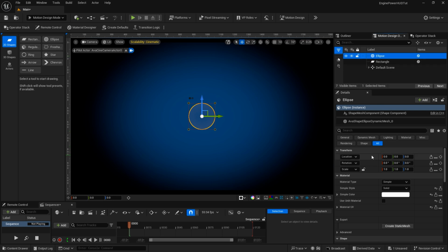So I'm going to bring this forward just a little bit. So I'm going to click on the location X property right there, and I'm going to set that to -1. You'll see now that it pops out in front of our background. Earlier, they were being mixed together, and that could cause rendering issues. So we are going to have to stack these layers ourselves.